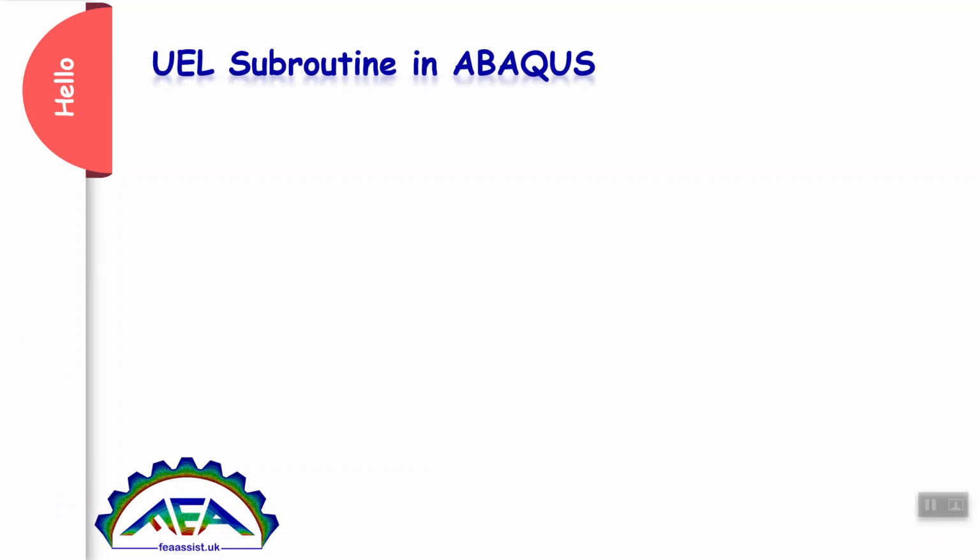Hello, you want to learn UEL subroutine in Abaqus easily and quickly. UEL is a subroutine to define a new element in Abaqus. Consider you have a one-dimensional element with points A and B. For example, temperature in this element is interpolated between the temperature of point A and the temperature of point B. So an interpolation function computes and defines the temperature at any point in this element.